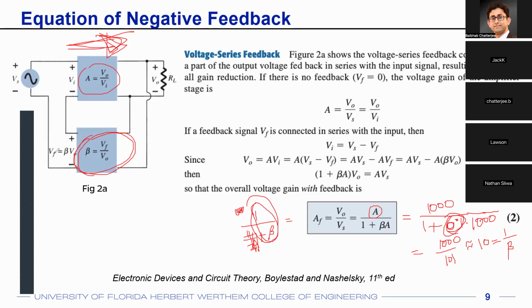That's because when you buy a set of resistors, generally they are manufactured in the same batch. And the manufacturing variations in the same batch generally go in the same direction. So if you're buying, let's say, 5 resistors, the values could be 1 ohm, 10 ohm, 100 ohm, 1000 ohm, and 10,000 ohms. Generally, if you see the 1 ohm resistance has become 1.1 ohms, the 100 ohm resistance will probably become 110 ohms. And the 1 kilo ohm resistance will become 1.1 kilo. Generally, they go in the same direction if it is the same batch, because manufacturing variations are not random.